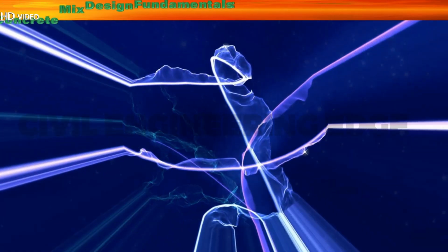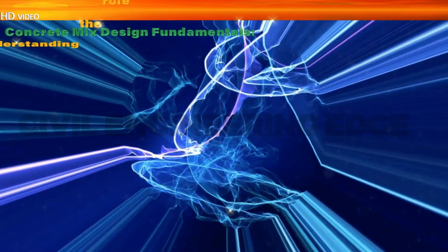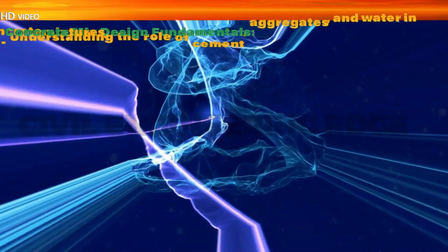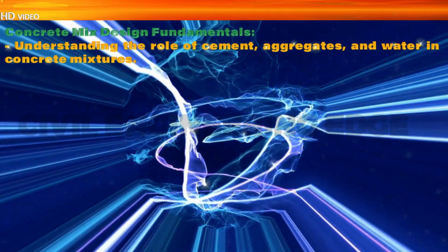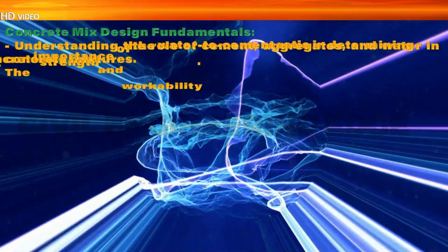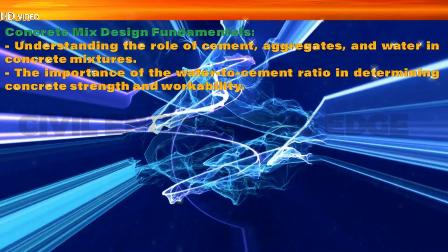Concrete mix design fundamentals. Understanding the role of cement, aggregates, and water in concrete mixtures. The importance of the water-to-cement ratio in determining concrete strength and workability. Introduction to common concrete mix design parameters: slump, compressive strength, and air content.